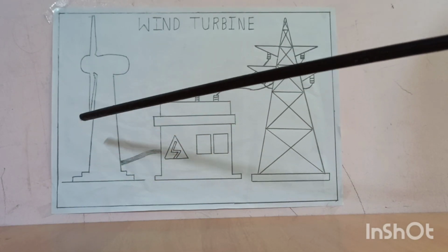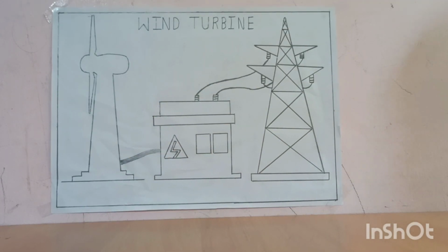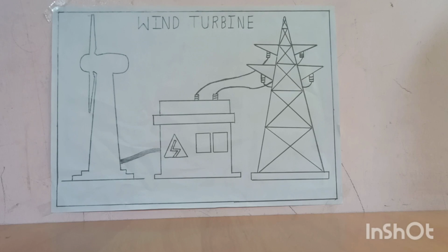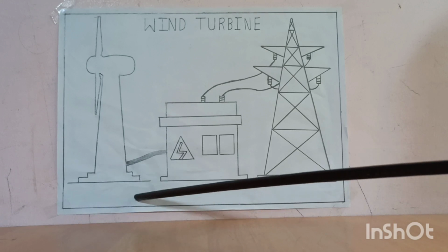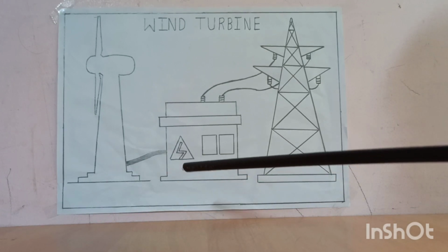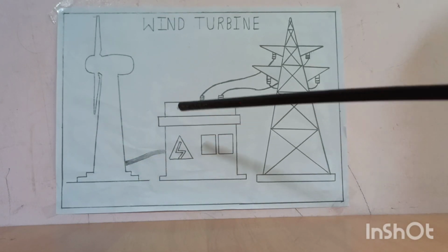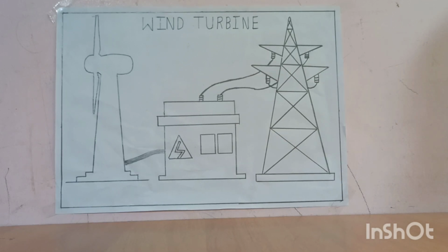and monopiles. Monopiles are used especially in offshore turbines because we install the turbines at sea, and the seabed is at a certain depth, so to install the turbine on top of that we need a monopile to withstand the entire load. And the tower foundation is specifically for onshore as we install on land. And the transition piece, which I will show you in the model, is for offshore as well. After the monopile comes the transition piece, and then the tower is raised.